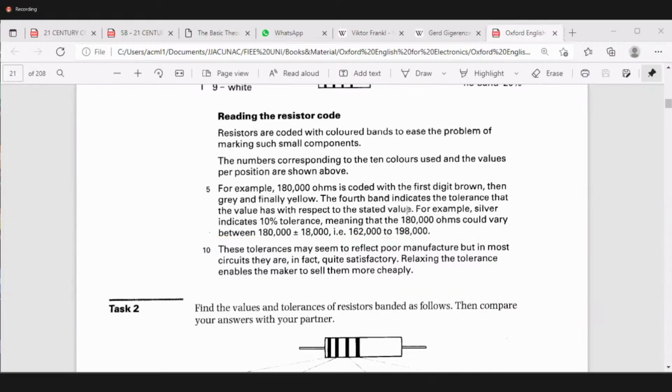But there is a problem with the tolerance. Tolerances can be maximum 20%. With 20%, they have established that they wouldn't represent a problem, depending on the type of circuitry. For example, if you are designing some medical equipment or some precise equipment, definitely you need to work with the most accurate components.